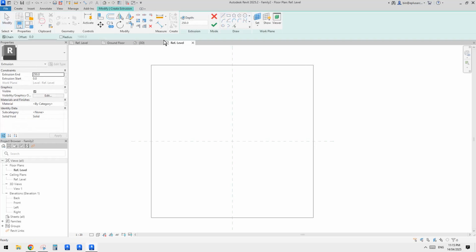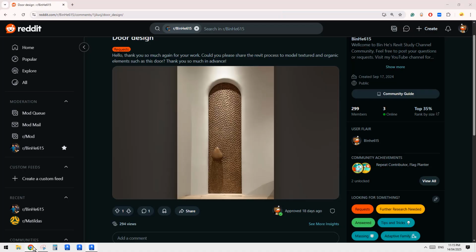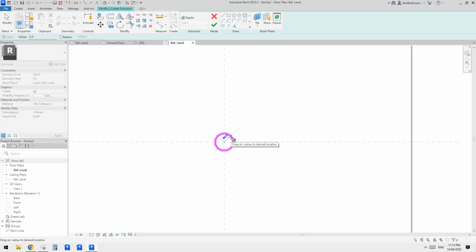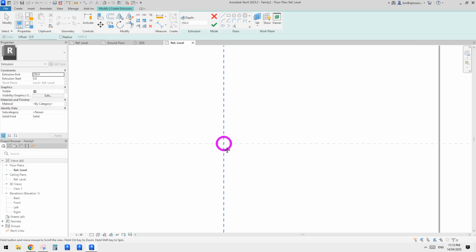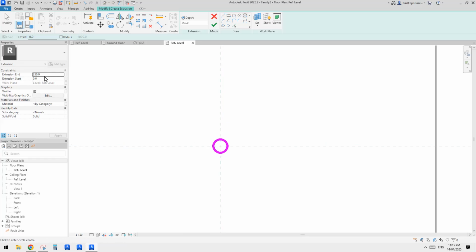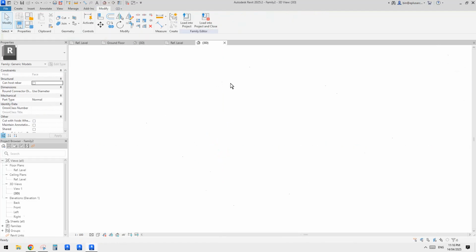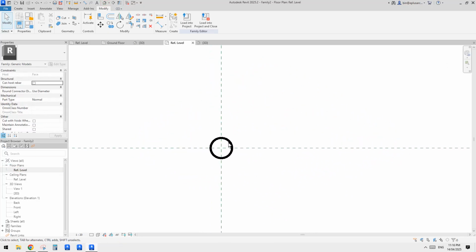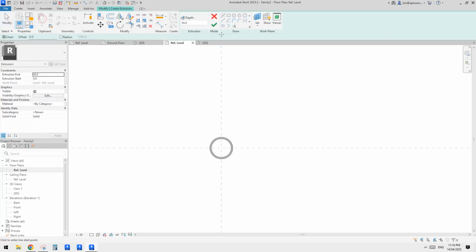I think I'll just do an extrusion. Because it looks like it's off the door, but there will be some connection, right? So for the connection, I'm not quite sure. Maybe just do an extrusion, right? So maybe 50 from the base. So let's go to 3D view. So from the base, that's 50. All good. And then we need to add another one, right? So create another one, extrusion again.